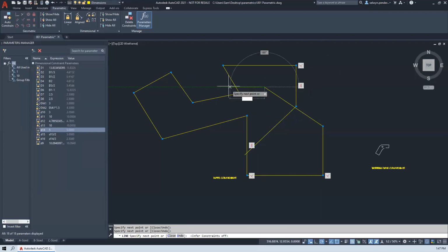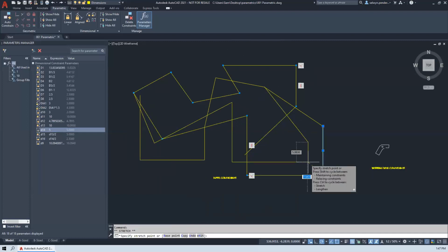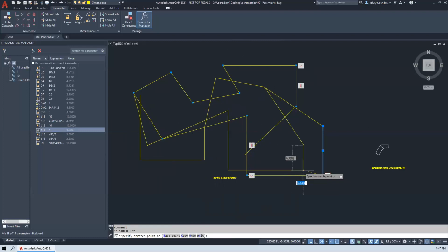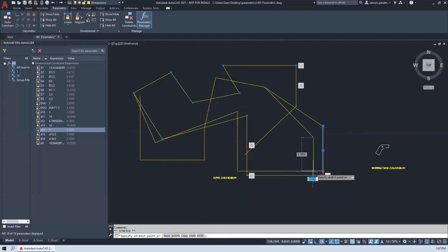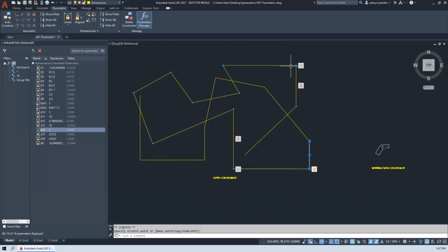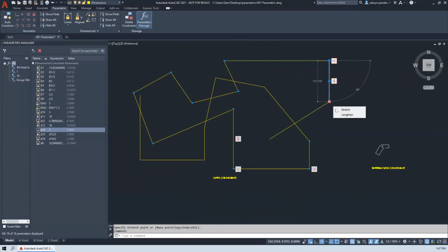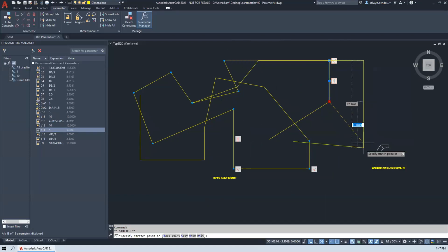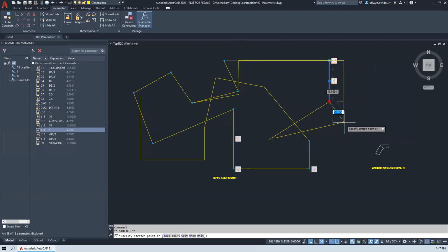If you want to stop using it, just keep going and you'll find that now no more constraints will be added. When we move this around, we should find that our right angles stay in place. Same with these ones up here. And we'll find that we can't change that angle because we've got vertical and we've got that perpendicular constraint applied.